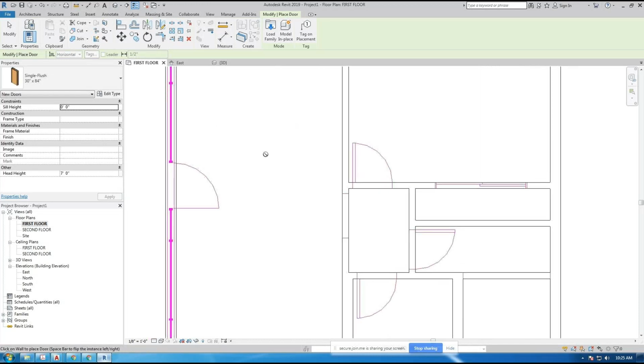and it won't work unless it finds a host. What that means is, such commands in Revit need a host. It needs somebody, someplace to put that object. You can't have freestanding doors out in space somewhere. You can't have windows floating in space. You have to have a wall. Therefore, the wall is the host. You can't put a light fixture in Revit unless you have a ceiling. Therefore, the ceiling is hosting the light fixtures. So, doors need a host, and the host is the wall.